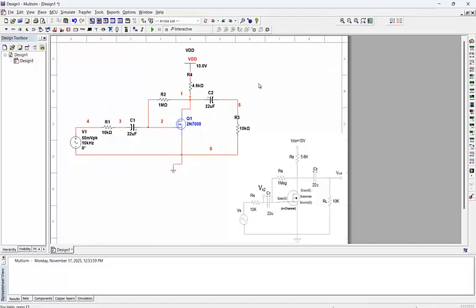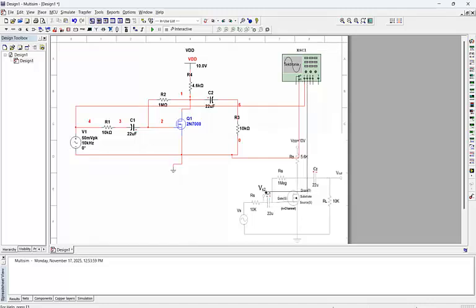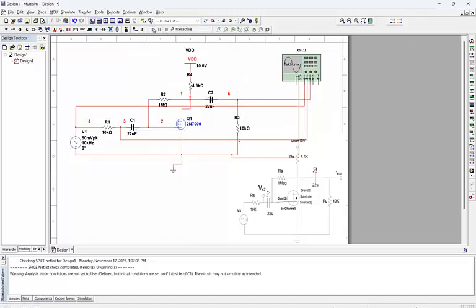And that's it. Let's get our Tektronix oscilloscope from the right, connect the ground, and we have 3 things to measure. The first channel is going to the input. The second channel is going to this point, which is between the resistor RS and C1, the capacitor. So put it here in between. The third one is connected to V output, which is between the second capacitor C2 and RL, which is here. And now let's run the simulation.